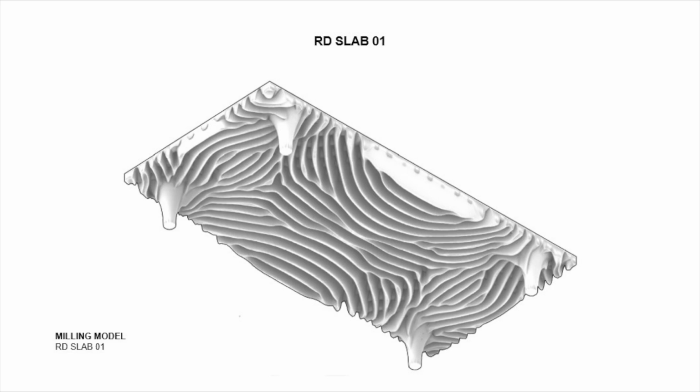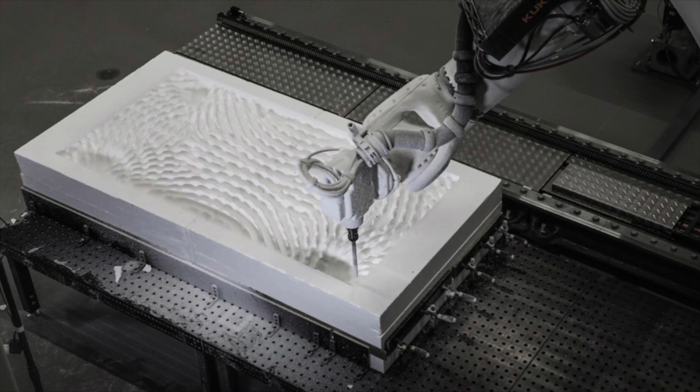Of course, you see just an image, but then you can use the information of the grayscale image, giving variable thickness to the structure, and combining that in different ways. And this type of object is produced with concrete, but before that, we had to mill a styrofoam block in order to have a formwork to pour the concrete inside. And in order to do that, you also have to take care of something else. Similarly to how you print clay, in this case, you have to think of what are going to be the trajectory for my robot to mill.